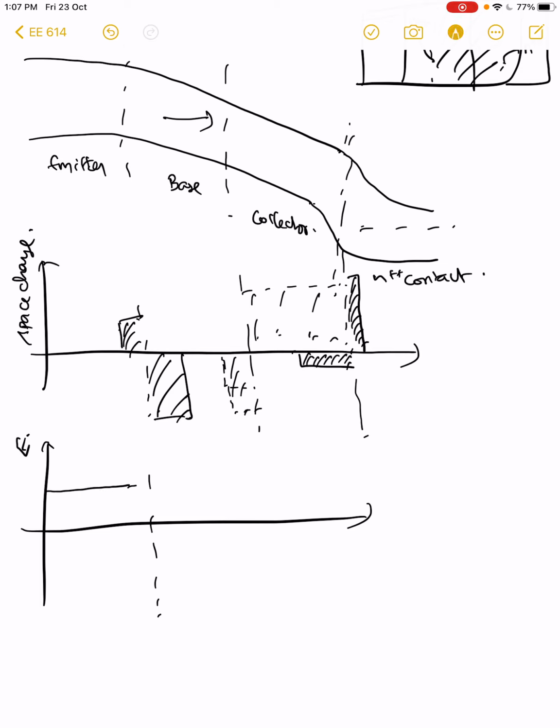You have a dip in the field, a much smaller dip on the emitter side, a reasonably larger dip on the base side, and you have a PN junction, reverse bias, so you will have positive charges here and then a much slower decay, right? And because you have an n plus n junction, the electric field will look something like this. This is the ideal case, ideal low injection.